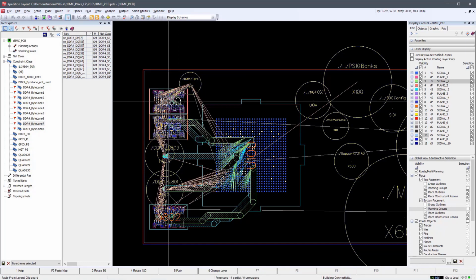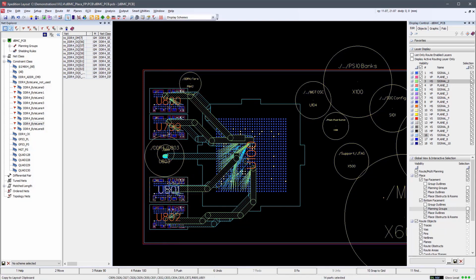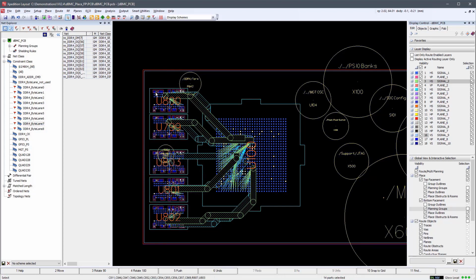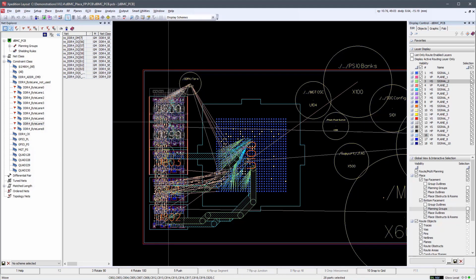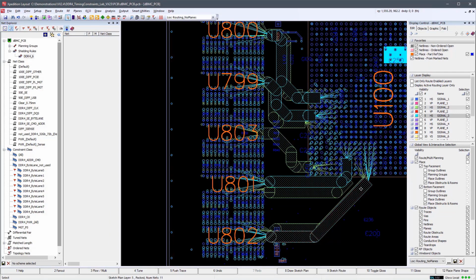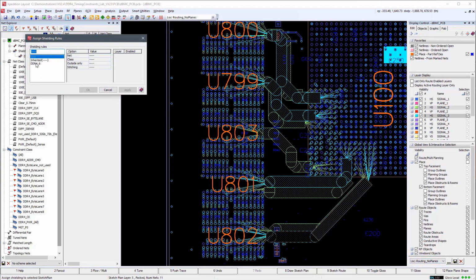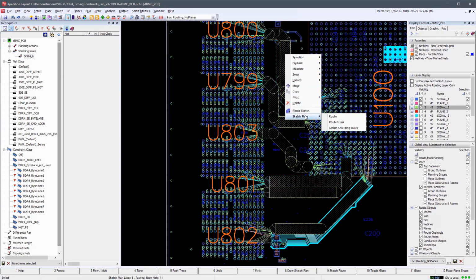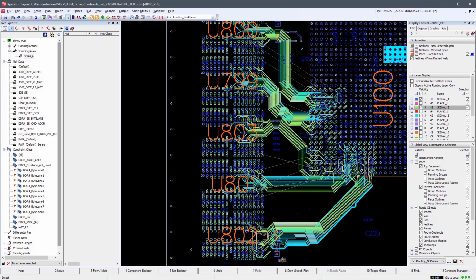As we continue placing copied circuits, we will use the hover alignment feature to ensure each circuit is placed along the same y-axis. As we modify some of the placed parts, the sketch plans remain, adjusting to stay aligned with their associated components. Sketch planning allows the designer to add shielding rules to assist with high-speed design requirements. Simply right-click over a sketch plan and choose a shielding rule created previously using Net Explorer. Once we've made our final adjustments to the sketch plans, simply select all the sketch plans you want to route and choose Sketch Route. The byte lanes will quickly and easily be routed.